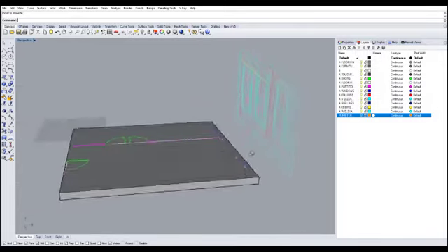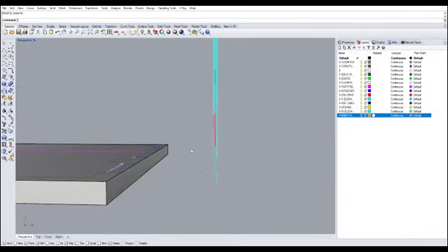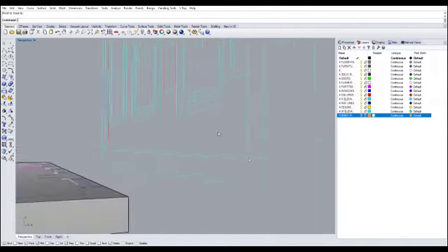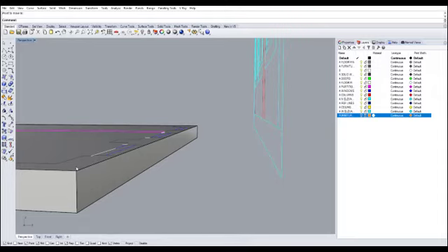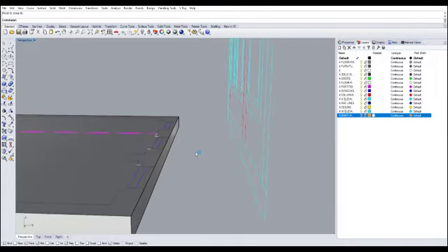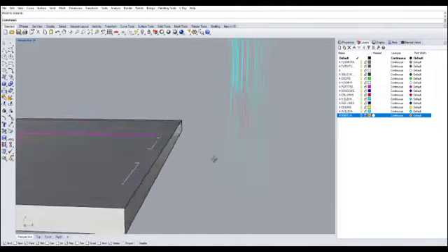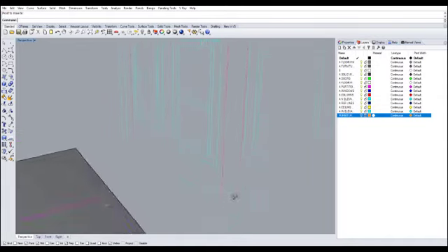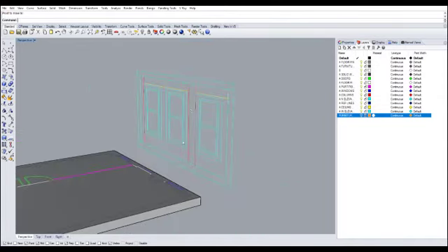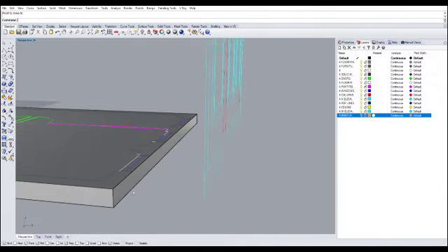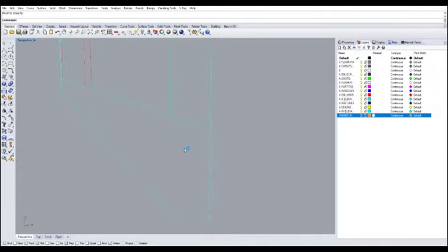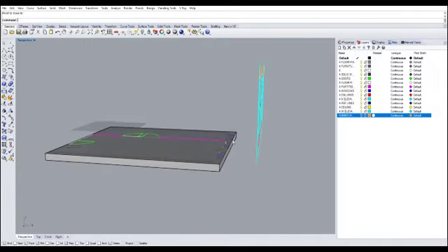The best way to do that is to have our floor plan sit exactly next to our two-dimensional elevation. So we're going to line up the floor line of the 3D object to the floor line of the 2D object, so that they're exactly against each other, and when we extrude an object, we have our direct reference right next to it. Easy convenience. In other words, let's move our floor and our floor plan and match it against our two-dimensional elevations. Let's do that.